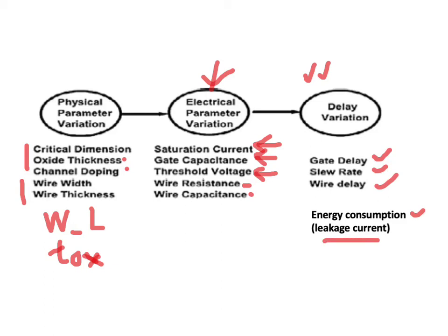That is the current flowing from the source to the drain of the transistor when there is no channel established by a gate voltage across the transistor. So the transistor is theoretically supposed to be off, but because you have a non-zero supply voltage applied across the drain to source, there is a small amount of current flowing, and this is the leakage current, and this is what contributes to the heating and a significant part of the losses of a